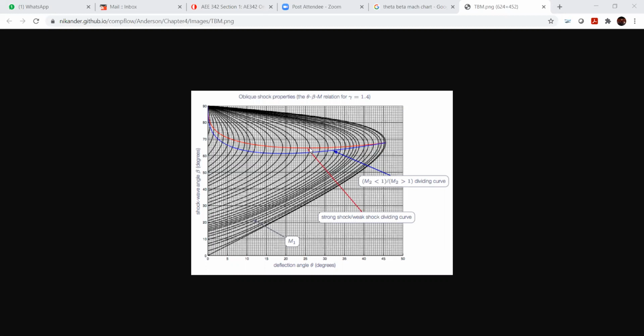Tying this up to our second point that we just discussed, if you are below this theta max value, you are moving along this curve for a given Mach number, which means that for a given theta angle, let's say 15 degrees, this 15-degree constant line cuts this curve at two places, one here, and if you go up, one somewhere here.